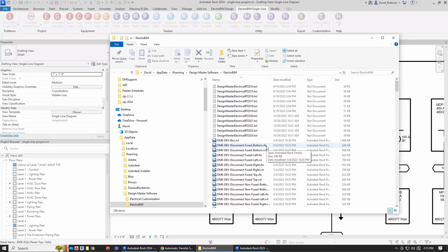can't downgrade Revit files. So as we're making custom files, you want to make sure that you're working in the oldest version of Revit that your company wants to support. We're shipping 2018. You might not be working on projects that old. Maybe you want to use 2019 or 2020. Just make sure that if you're working in 2024, you're not going to be able to use that file in 2023 anymore. So just be aware of the version of Revit that you're using.